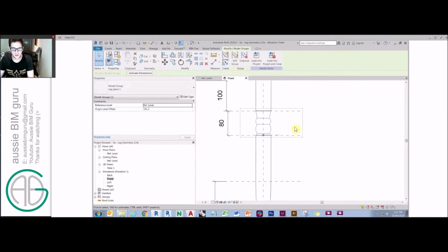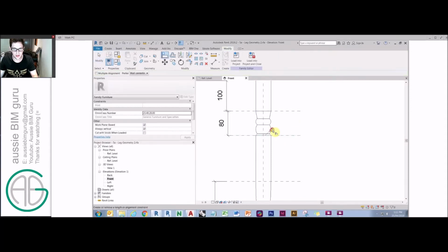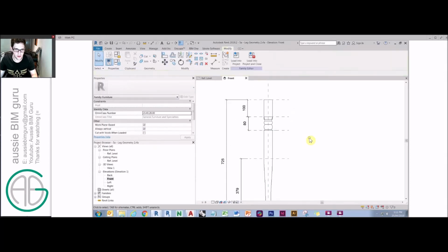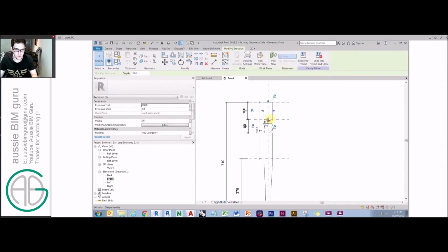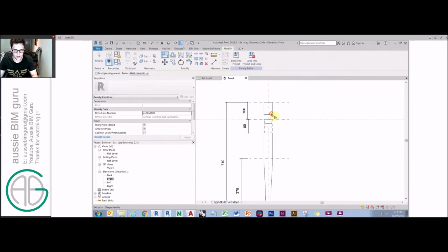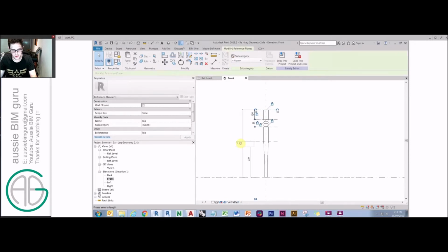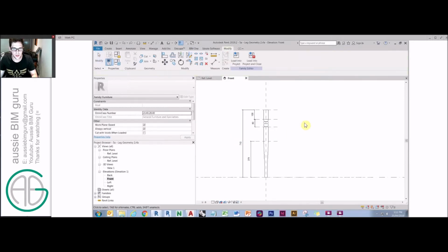And then at that point, we've got a piece that basically moves freely. And we can lock that. And now when I change this, yeah, so now you can see it's working. The only thing we need to do is constrain this extrusion here. Great. So now you see as I move this up, the leg piece will move up as well. And that allows this to be parametric. So if I make this a meter, you'll see that my leg can adjust. So this is prepared basically to be parametric in the next stage.